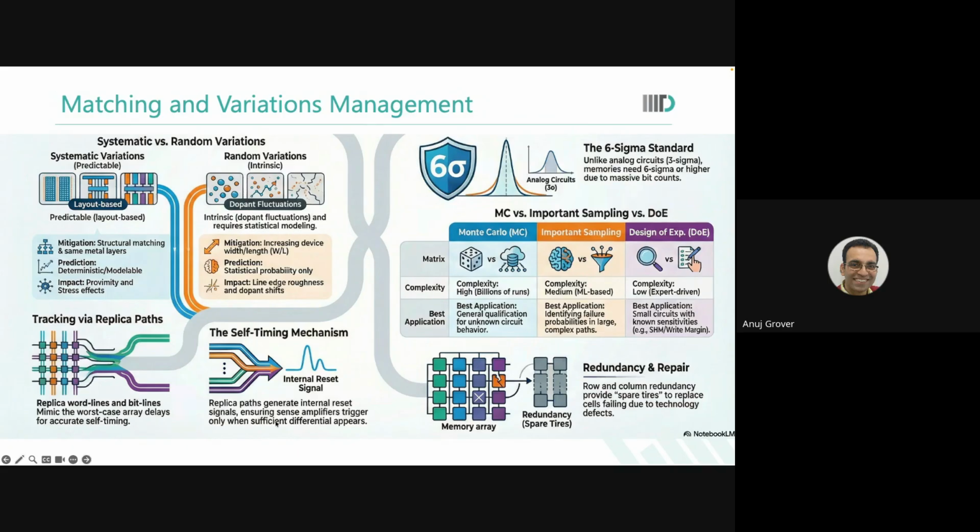And we also had a design here where SAN was not triggered from the control region. We said, okay, why add this RC? I will have my replica word line right next to the IOs. And from this replica word line, I will have a small mini bit line coming in, which would trigger the local sense amplifier there. So what have you done? You have removed the SC and RC even in SAN triggering. Are you able to see this?